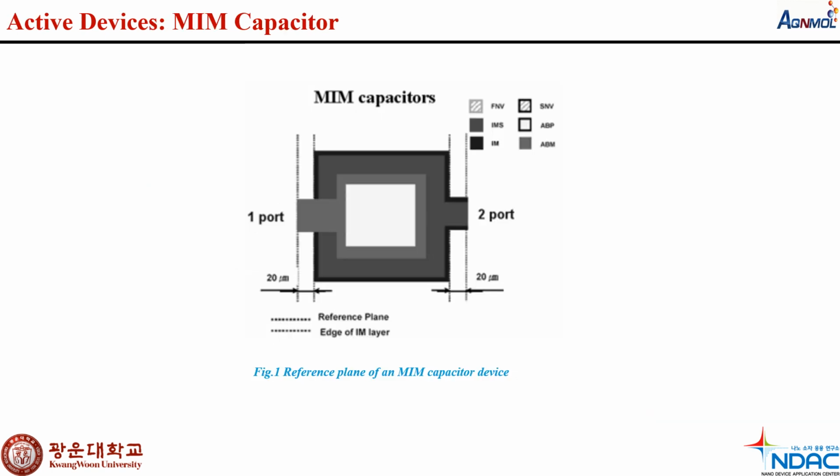In the passive device, another important factor is the MMIC capacitor. Both overlay capacitors and interdigital capacitors can be used in MMIC technology. Interdigital capacitors can be used for values up to approximately 1 picofarad, above which their size and the resulting distributed effects prevent their use. The most popular type of capacitor has become the MIM.